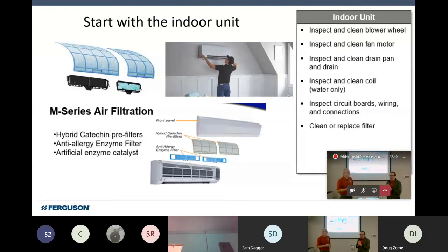One of the things that I would really warn you to stay away from is self-rinsing coil cleaners. Oftentimes it's suggested, and as a service tech, we think, oh okay, I can just spray this on, it'll condensate, it's in the air conditioning season, just rinse that off.